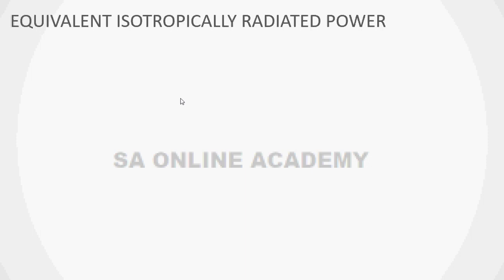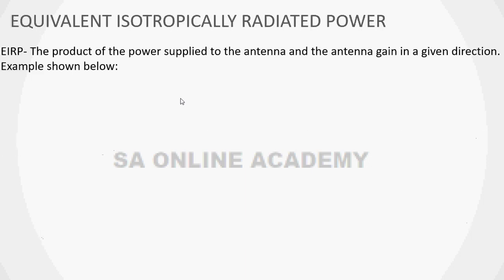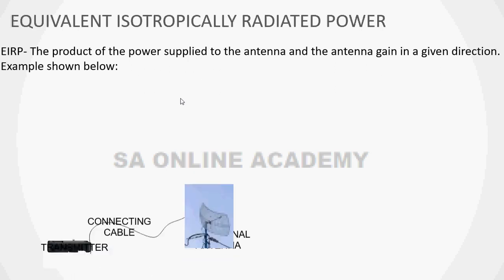There is a limit, or transmit power guidelines, for each country, so you have to comply with these transmit power limits. The other way is that you have an input power of 1 milliwatt, and using a directional, focused or concentrated antenna, you radiate a power of 4 milliwatt. This increase in power is called EIRP.